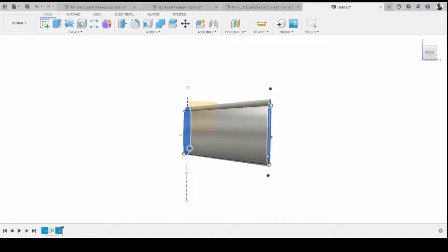Now you can see what Fusion does. It makes a straight loft from one to the other. So if I move that across, you might say it'd be a wedge. But there is one thing you can do in Fusion to curve these off, tangential, or perpendicular, to that profile. So if you go over to profile 2, where it says connected, we look at the drop-down menu and change it to direction. That basically puts that curve in, so it's starting off at a nice smooth tangent, a perpendicular, if you like, tangent to that one. So then you could mirror it across.